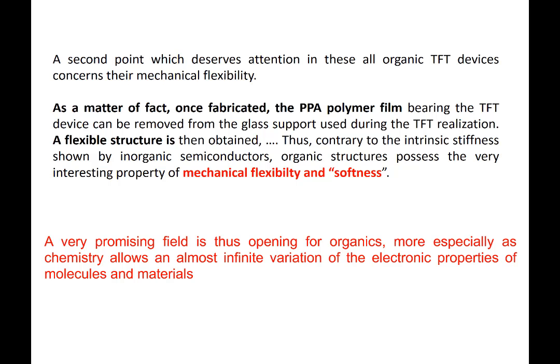Why did blue LED not develop? Because they had only gallium nitride. Gallium nitride was giving them so much problem. Right? If I had lots of other materials, I would have quickly abandoned gallium nitride and gone to another material. There is no other material. So for crystalline semiconductors, there are only a handful of them available. But the moment you go to organic and amorphous, you have a large variety of materials available.